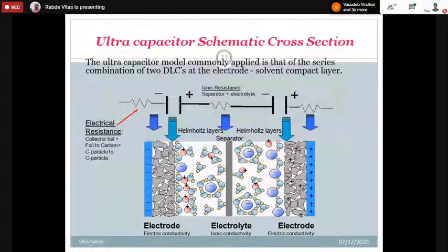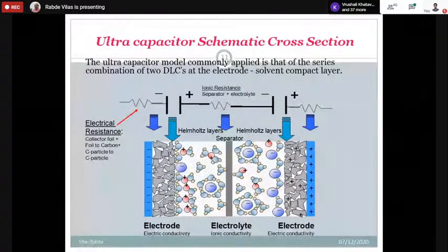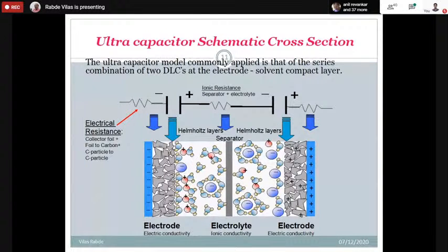So this is an equivalent circuit of a supercapacitor. Two capacitors are in series, and those resistors represent the electrical resistance of the packaging, especially the joints and welding. They are responsible for the losses, or tan delta losses, as the capacitor industry calls them. And there are two electrodes separated by a dielectric. That's why the capacitance value is always lower than the value during manufacturing, because two capacitors are connected in series.